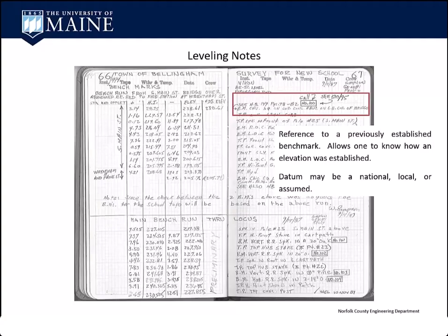And he's saying, call this number 100. I don't know what that's all about, but if you were going to use this information later on, then you might want to look at this. There's no datum called for here. It's 1987, so I don't think 88 was established yet, so it's all 29. Or is it? It could be an assumed datum.